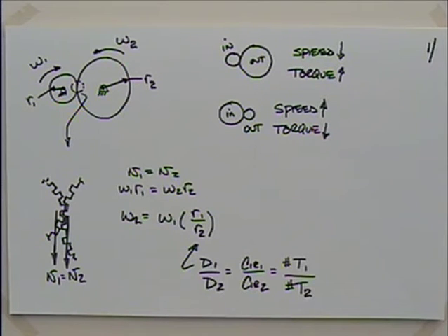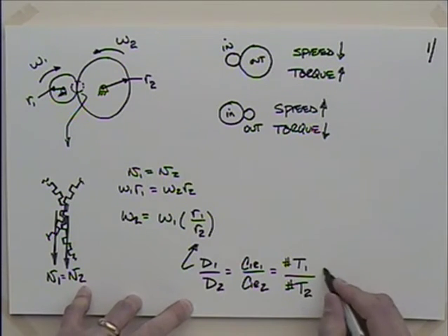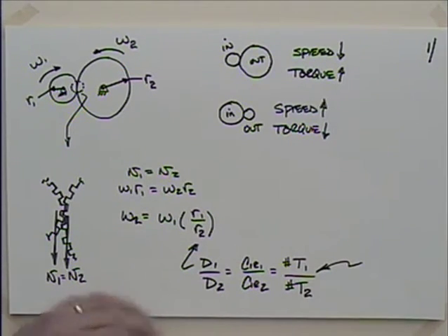And the tooth count's kind of nice because I don't have to break out any measurement instruments and try to figure out whether I'm talking about the root radius or the radius at the end of the gear tooth. I just simply count gear teeth and make that ratio work out. Probably next week or the week after, I'll bring a transmission into class and we'll go through this for the different gears and see the power flow through that. And we'll check out the ratios, and we'll do that just by counting the gear teeth. So that should hopefully be a good exercise.